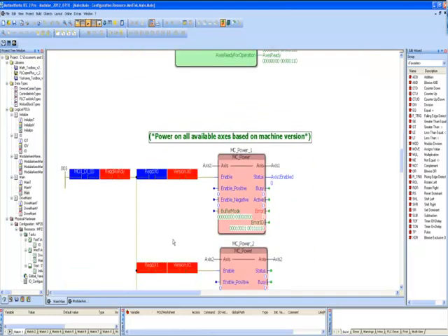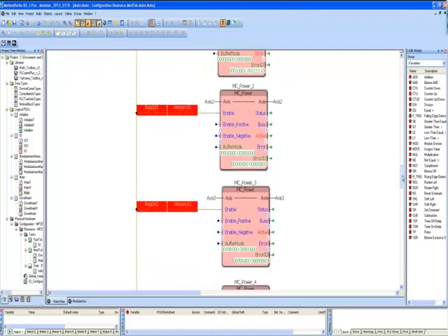And you can see here that the user's required axes is the same as the number of axes online, and those 2 axes are ready for operation. This basically forces required axis ready output to also come on, and now the user can go ahead and use those 2 axes and run the machine with those 2 axes. So that was just a quick, live demonstration of what happens if a particular axis is removed from operation. And the same is also true if the third axis gets added on, or in this case, if the first axis gets added on while the machine is in a standstill state.